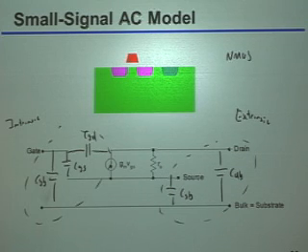Okay? Does this make sense? So in other words, if it's a transistor, it's an MOS, right? So an MOS is indeed a capacitor, right? So the CGD and the CGS are directly related to the fact that it is an MOS transistor. Whereas those other capacitors, it could be some other kind of transistor or just basically any other thing, and they exist because of the way we happen to be building it, not because they intrinsically have to be there to get a transistor to work. Okay, great. That's really more of a naming thing, just because you may hear intrinsic versus extrinsic. Practically speaking, it doesn't matter too much.